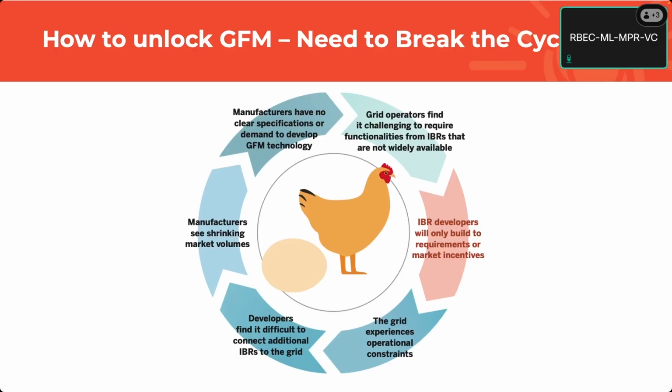The other thing that confuses me is some of the inverter manufacturers are saying, we don't care what mode you operate it in, we can flip it. Other manufacturers are not saying that. I want to be fair to the developers and the OEMs who are saying this isn't actually free. That's probably true. To say that changing it from grid following to grid forming is completely free may not be true. There might be extra engineering involved.